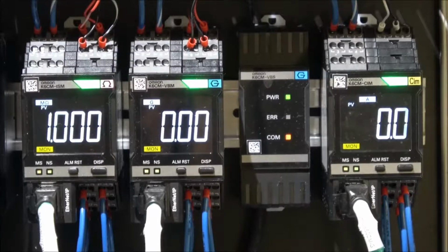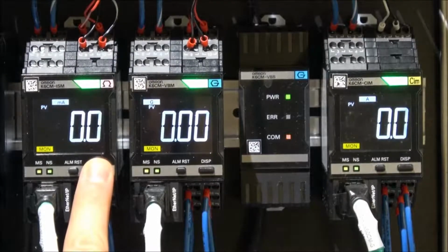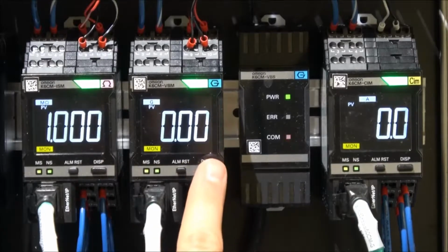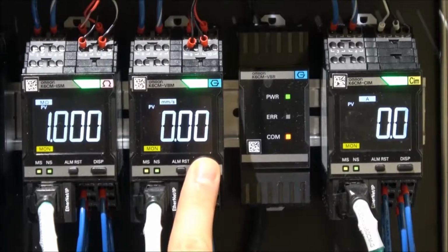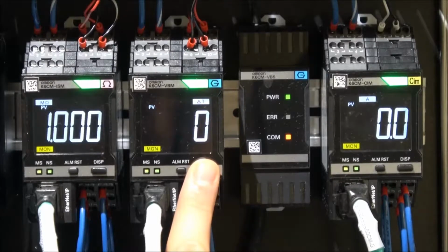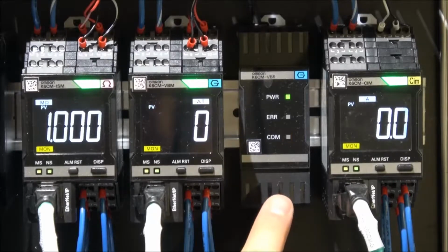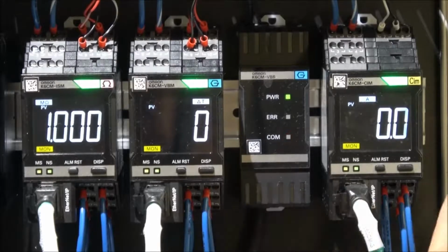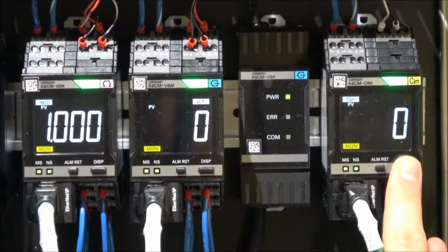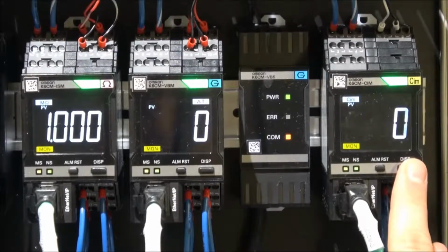You can see the variables that each K6CM sensor is monitoring locally on the display. For the insulation resistance, you see mega ohms and milliamps. For vibration and temperature, you see G's of acceleration, velocity, temperature, and then delta temperature between the motor and the ambient. Right here is our vibration amplifier, which is also measuring the ambient temperature to compare to in the delta T. And lastly, the current analysis will show the current as well as the degradation level, the deviation from a uniform sine wave that will result in some kind of warning or critical threshold.